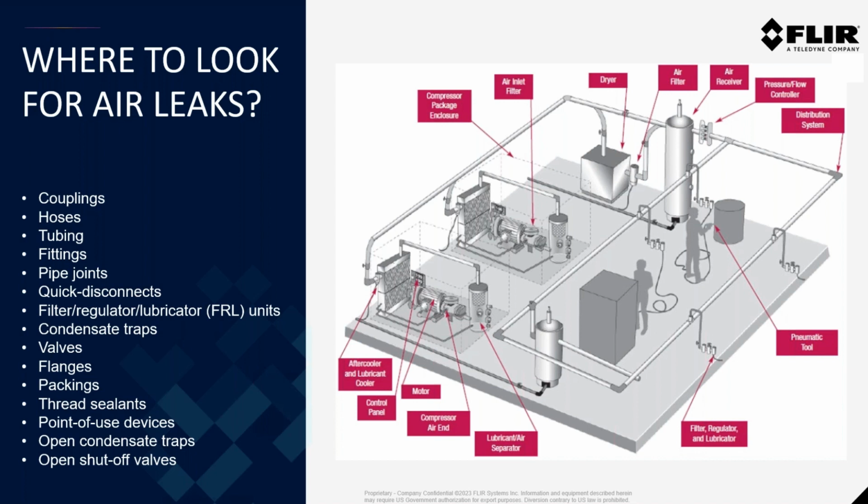These systems, the truth of it is they leak a lot because they're complex. There's a lot of connections, and ultimately this is an issue where unless you are physically very, very close to a leaking distribution line, you may not hear the sound or the hiss, if you will, unless everything is very, very quiet. Or you're using other prescriptive methods like the old soapy water around flanges or connectors. It's a time wasting activity. It takes a long time to do it versus using the acoustic imaging technology.